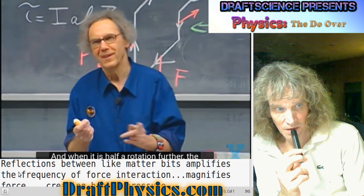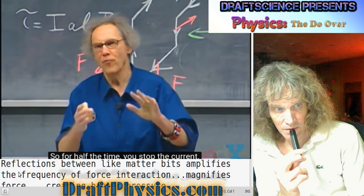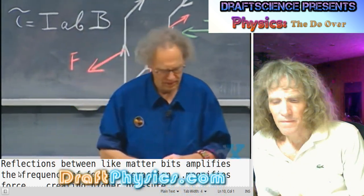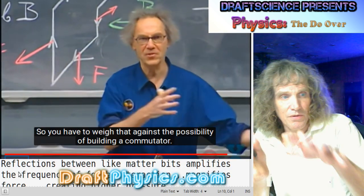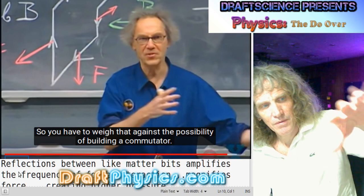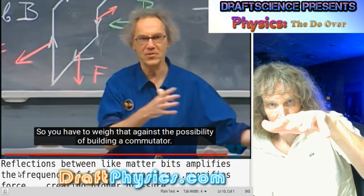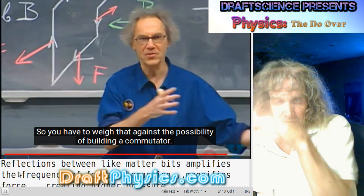And when it is half a rotation further, the torque is there again, the current is there again. So for half the time, you stop the current. You'll see that's very easy. I give you some hints how you do that. It's just how you make the brushes. You just have to go 90 degrees past, and then you can put the current back on, and then you flip here and turn it off again.